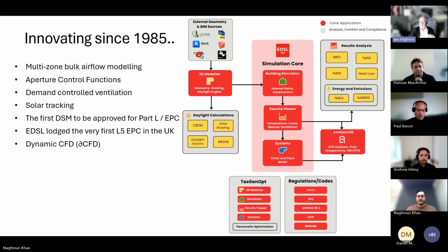and that was the first time we properly, fully integrated an airflow network, which basically took account of all the wind pressures, wind speeds, wind directions, gave you that sort of convective point of view, but also included the stack effect, which was effectively being driven by the building simulation. So this was the first time we coupled the building simulation, which is all about fabric and heat flows in and out of walls, etc., to a full airflow network, which was obviously being driven by wind speed and direction and the stack effects.